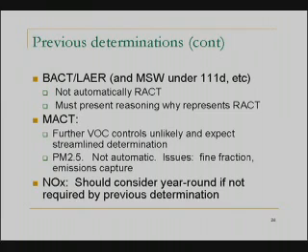Many MACT standards also address PM 2.5 and often the way that they require compliance is through limits for heavy metals. And again, for these MACT standards with PM limits, it's not automatic. There are issues with respect to the fine fraction. There are issues related to the degree of emissions capture that in particular should be addressed in determining whether a MACT standard would represent RACT under a PM 2.5 SIP.